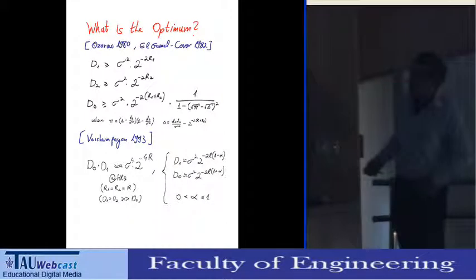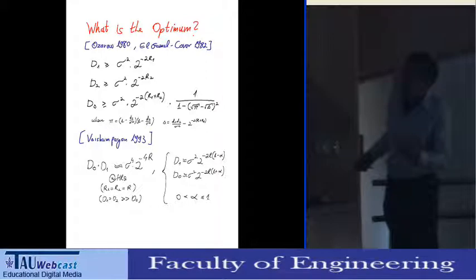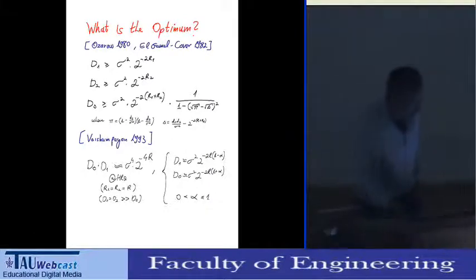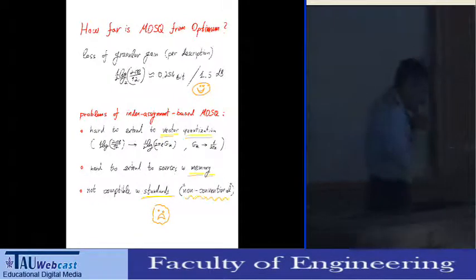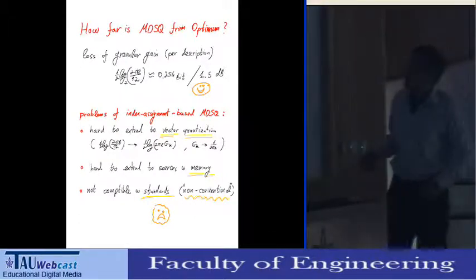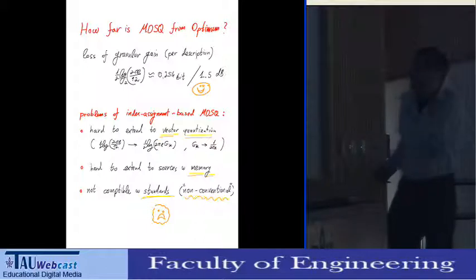And then I can think that there is a certain parameter alpha which goes between 0 and 1, and it tells me how much better I am when I'm getting both packets. I'm getting here in the exponent 1 plus alpha, and how much worse I am when I'm getting only 1 packet. Okay, so if this is the optimum where the index assignment in the matrix is standing, Vaishampayan showed that the loss is about a quarter of a bit per description, or 1.5 dB.